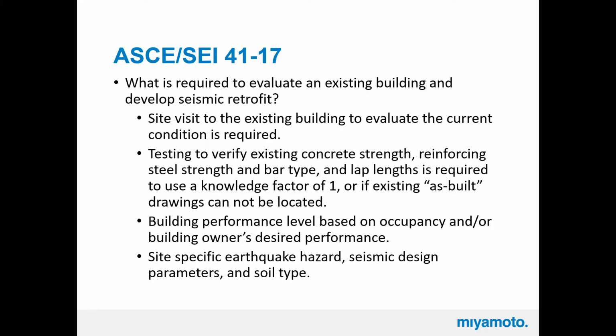As I said, site visit: we always want to visit the site if we're doing an evaluation, even if we have the drawings. If it's an older building, we want to ascertain that there haven't been modifications made to the building, large additions that we don't have any documentation on or anything of that sort. Or that they haven't cut big holes in the shear walls, if it's a shear wall building, or made wholesale structural modifications of the building. So it's always important to document that.